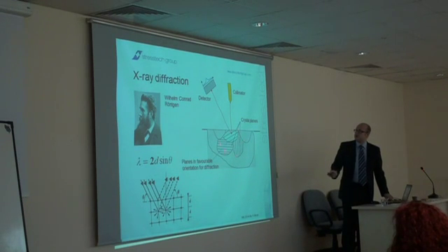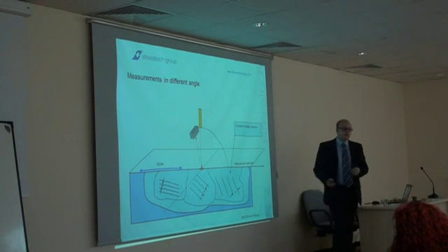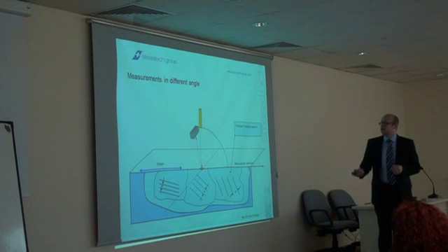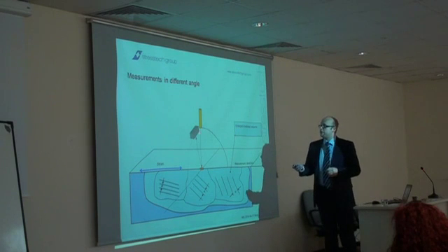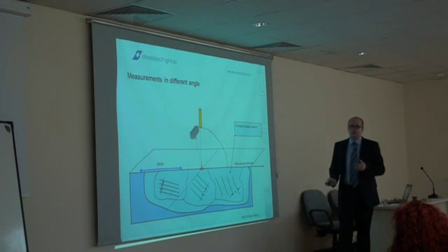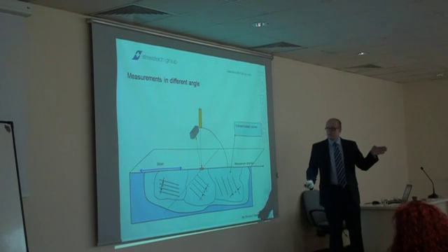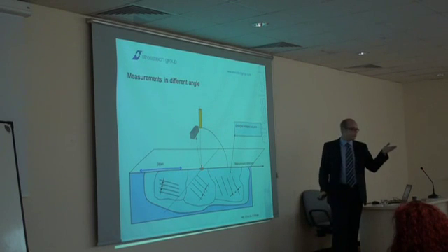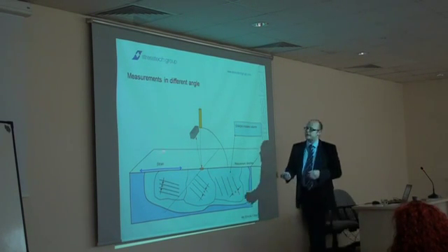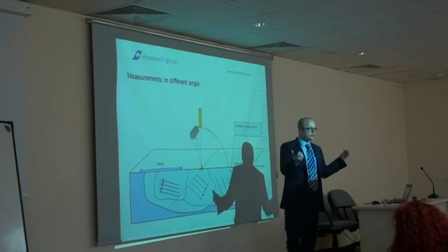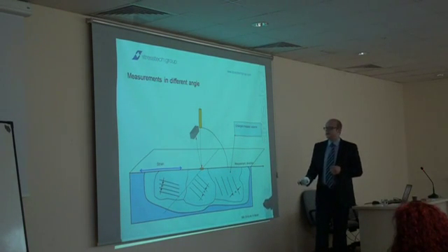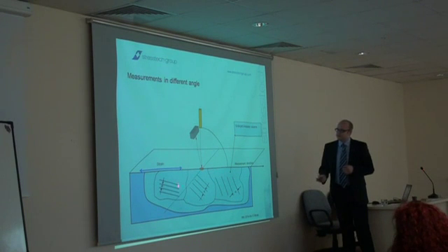So here are the crystal planes, and we have randomly oriented crystal planes under the collimator. Some of you already saw how X-ray diffraction works. We have to use a couple of tilt angles, like Zaim already showed you yesterday. At the first angle we detect the D0 value, then the D1 value, and then the D2 value. You can see from here that our strain direction is this direction, which means that we have a tensile stress in our component, which also means that our atom planes are like this.